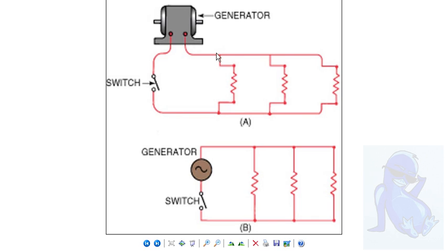And then you take L2, you put L2 on that side, L2 on that side, L2 on that side, and these are run in parallel. This is an electric circuit drawn in parallel. This is the same circuit drawn more simply with your power source, your switch, and it's kind of a ladder diagram where you've got 3 loads drawn parallel.